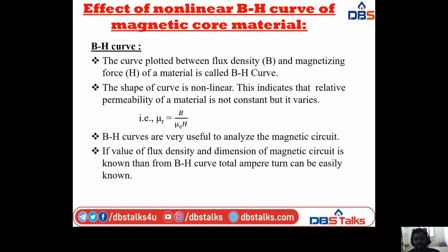BH curves are very useful to analyze the magnetic circuit. If the value of flux density B and the dimensions of the magnetic circuit are known, then from the BH curve, the total ampere turns can be easily known.